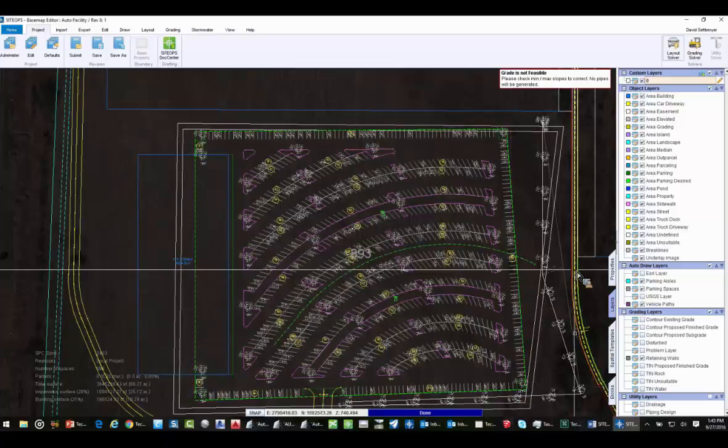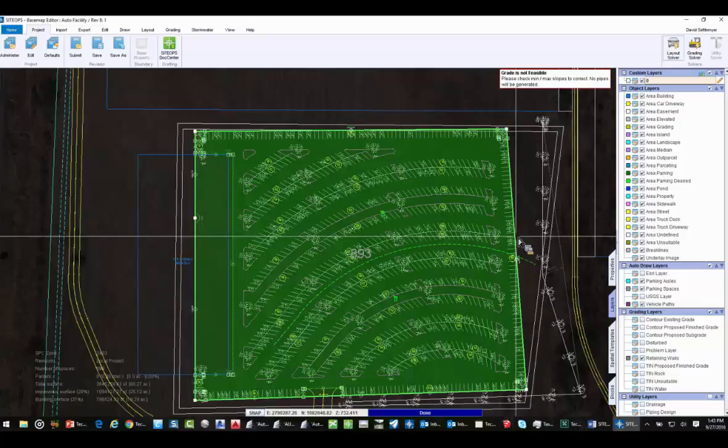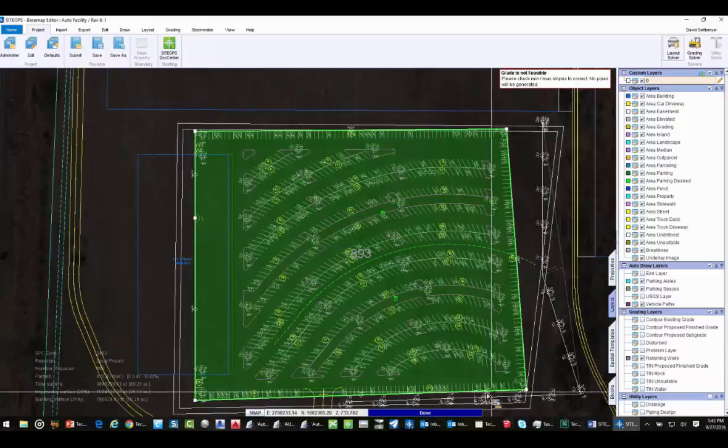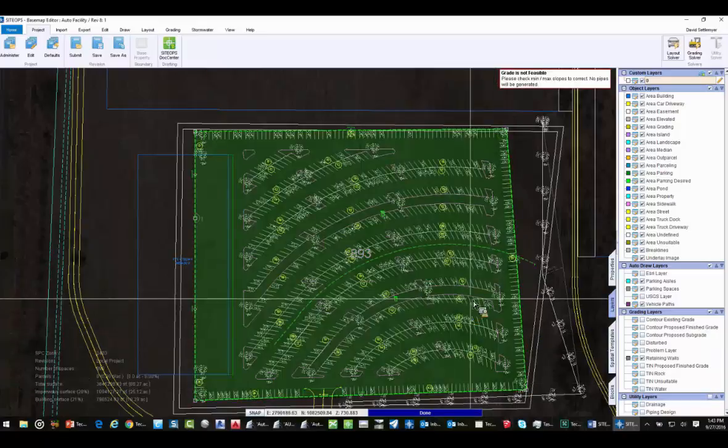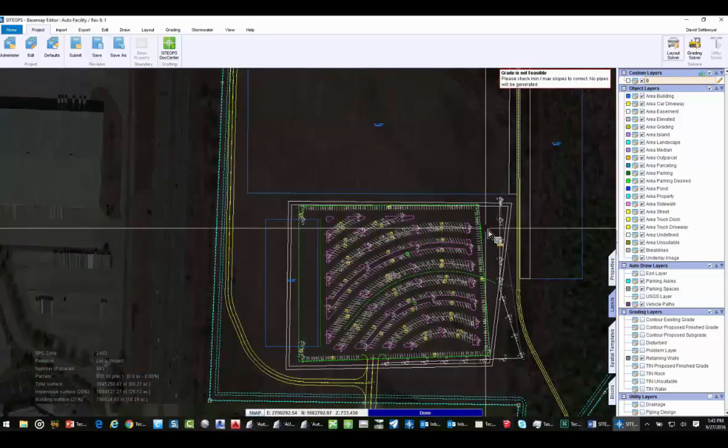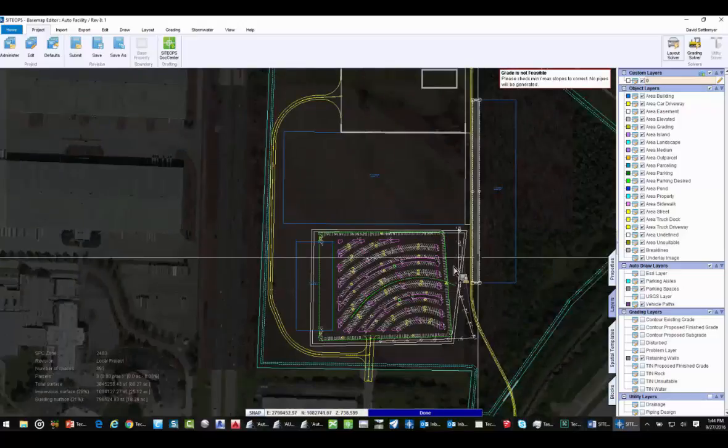What we want to do is similar to the way you saw the road profile. You can click the outer edge of a parking lot, for example, see that in the profile, and start moving it down and making it where I could control exactly how it drains. Come in and grab some of these islands and do the exact same thing. I can start manipulating individual areas and objects inside of SITEOPS to make that design a little more accurate. Again, we're still in the conceptual phase, but we want to give users the ability to be a little more detailed as we keep moving along in the project, and not always just go where the first 30% is. We need to get more to 50 or 60, because at 50 and 60% of documents, we're still making a lot of changes sometimes, and we want SITEOPS users to still have the ability to do some modeling and quick automation inside of that phase.